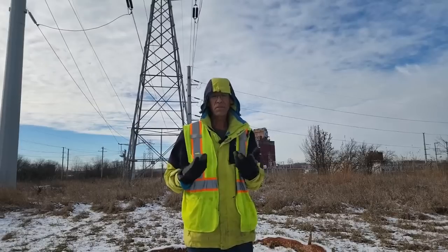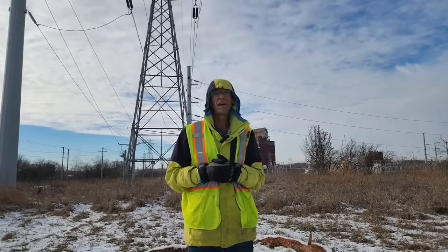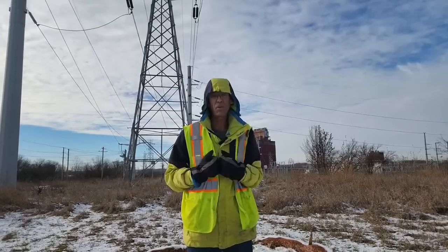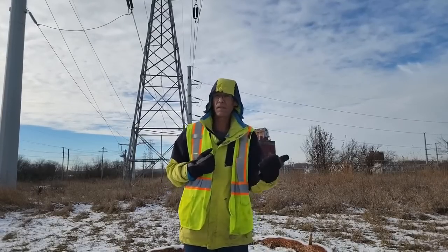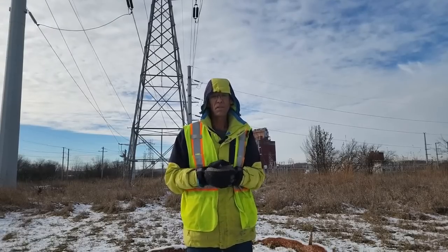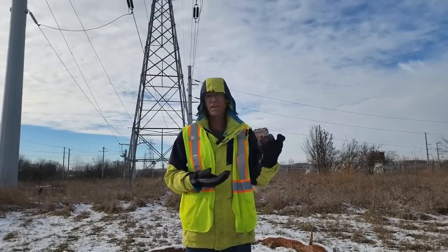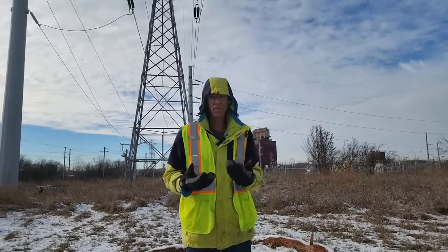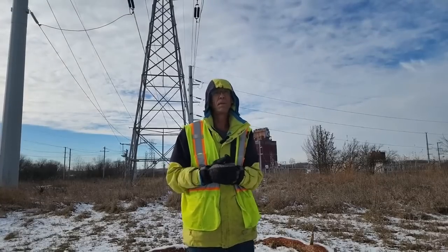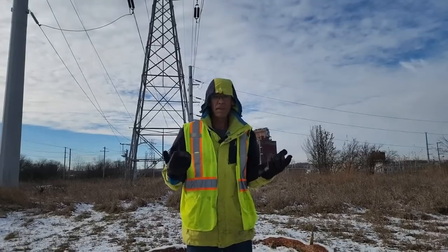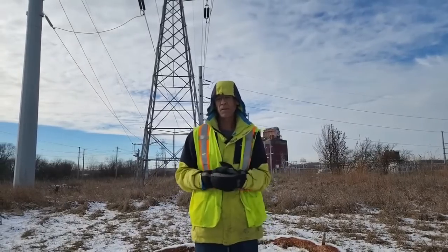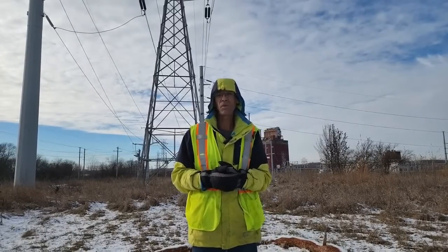Alternating current mitigation systems are installed because gas or oil pipelines receive alternating current voltages either by inductive, conductive, or coupling methods, where these voltages can reach dangerous thresholds for the safety of personnel, operators, custodians, or pipeline owners. But it also represents a risk for the mechanical integrity of the pipelines because it can cause accelerated corrosion.